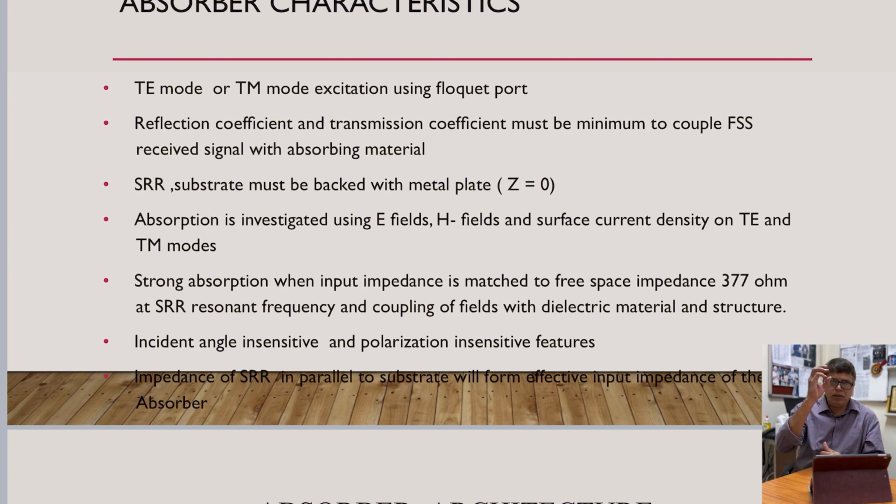A very important and crucial parameter for an RF absorber is that it must be insensitive to the angle as well as polarization of the incident wave. We generally feel that if circular polarization and wide angle response are created in the absorber, it means that from any direction the incident EM wave will be absorbed.